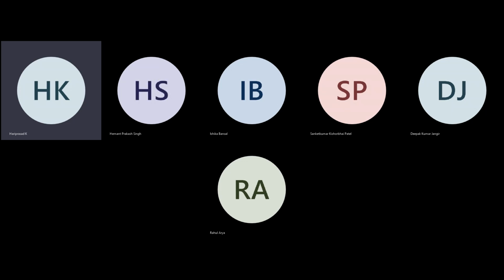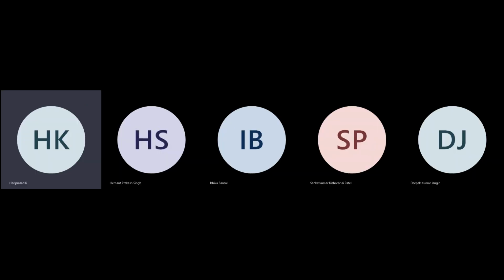The higher value of Kc could also result in sustained oscillation. We have seen Ziegler-Nichols and similar things. So you should move away and come to a space where you are conservative, in the sense that it is the most conservative setting. So you can freely play around with it. So that's the overall point.